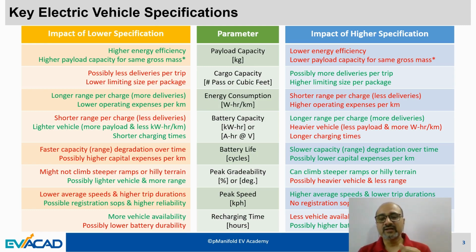The second metric is when the vehicle is running at, say, 15-20 kilometers per hour and encounters a grade: how much grade can it take before it fails to sustain 20 kilometers per hour? Both of these metrics are looked at.